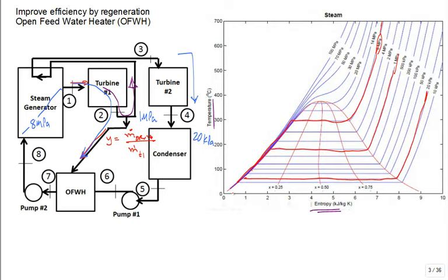True? Okay. And a lot of times when it comes to superheated, out of that steam generator at state 1, maybe it's at maximum temperature 450-ish degrees, and then that sort of sets where state 1 is, isn't it? That temperature, high pressure. Pass it through that turbine. At the best you can do, straight down.